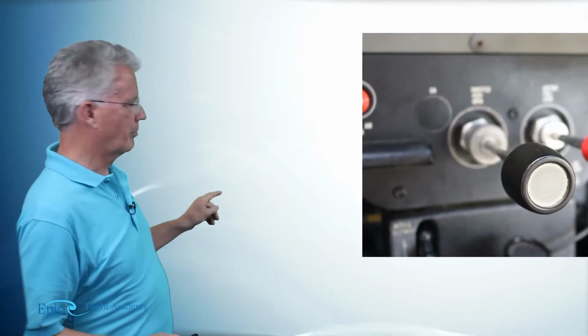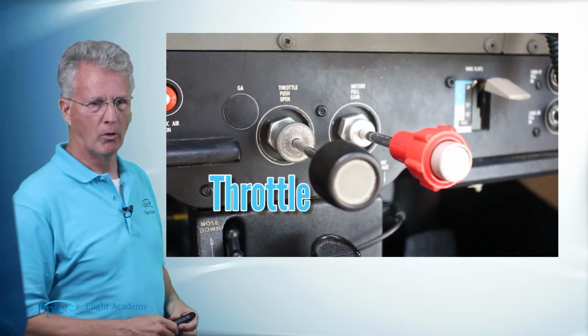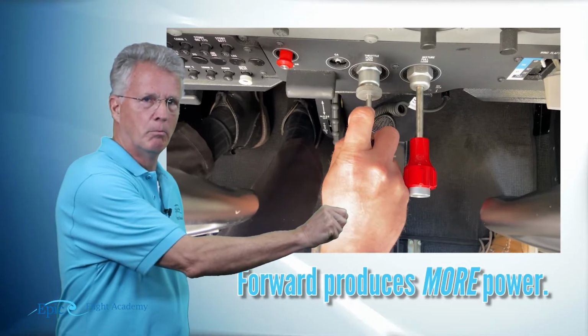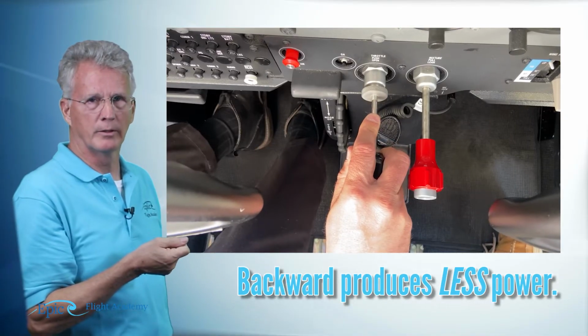Now on your panel, you have controls for these systems. And I want to point out 2 in particular. First of all, this black knob is the throttle. We're going to talk about that more later. You're going to hold that in your hand. Your flight instructor will work with you on this. Forward, more power or full power. As you pull it aft, less power all the way to idle.